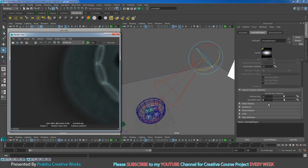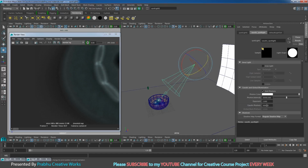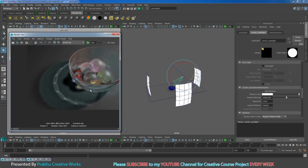So remember, when you increase the shadow rays and ray depth limit, your render time is much higher. And also when you increase your caustic photons, it also takes much higher render time. So remember both of these things.